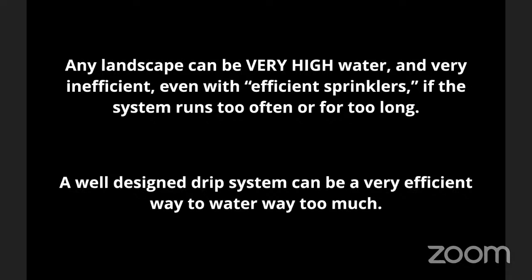If all of this math was just way too much for you, you can take a very old school approach, and there's nothing necessarily bad about the old school approach, where you figure out how long you need to water by running your system for a while, digging in the ground and seeing how deep the water has penetrated. And for most landscape plants, for water-wise stuff, you're going to want that water to have penetrated more than a foot by the time you're done watering. So figure out how long that takes.